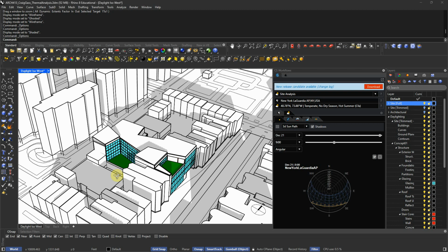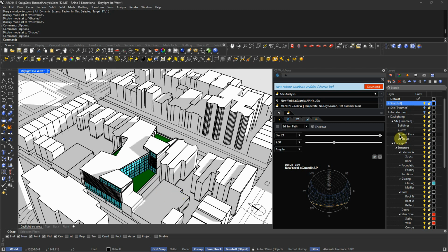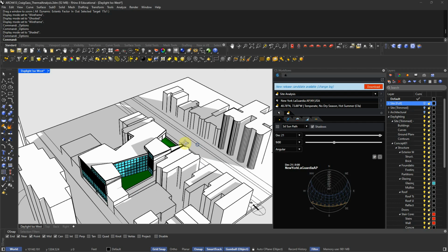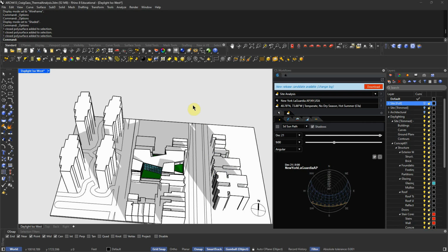The point is we need to see what's happening here at our building, right? But also we're trying to simplify the simulations later. So when we are doing daylighting, we only want to put into the shading layer the buildings that potentially will shade the building, because that just takes up computing power. This will work just fine for daylighting.